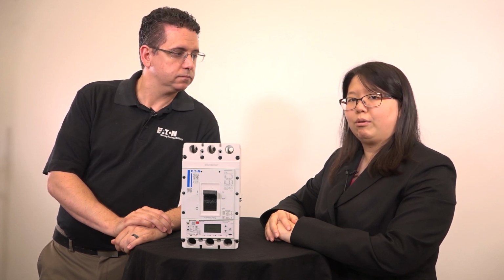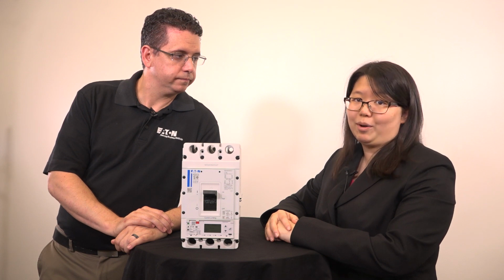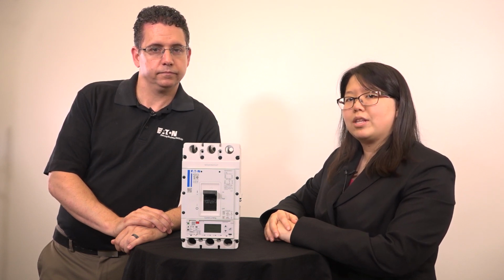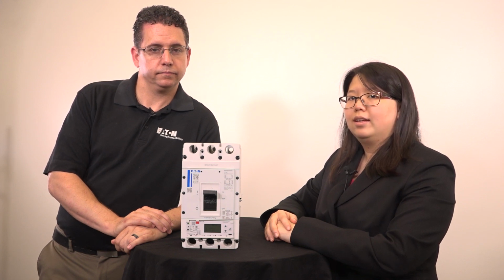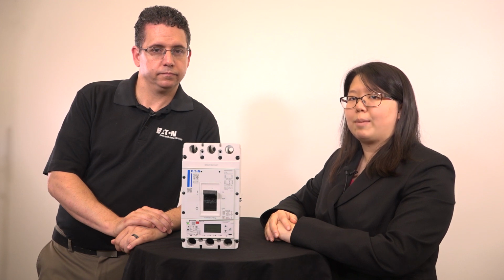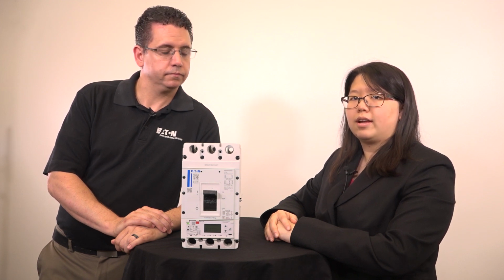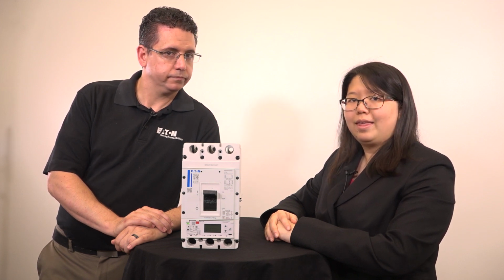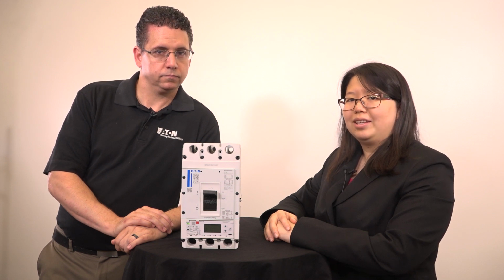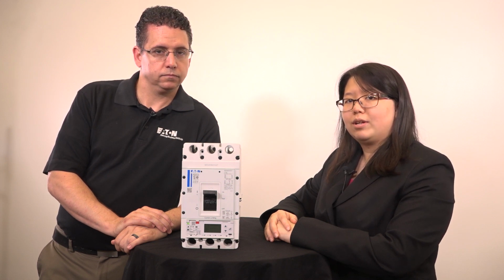This goes back to the point we made earlier about not resetting the breaker's diagnostics data. When we were looking at the reset screen, we mentioned that resetting the number of operations or trips on your breaker was not recommended. If you didn't watch the device settings chapter about resetting your diagnostics data, please make sure to do so. We go through this topic in a little more depth. Basically, resetting this just deletes all the data and makes your breaker health incorrect.